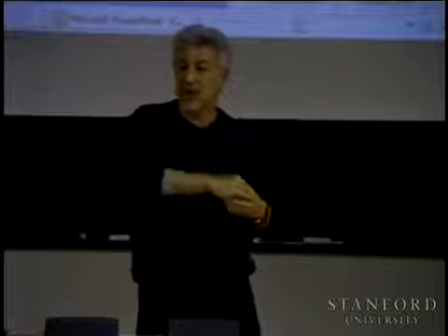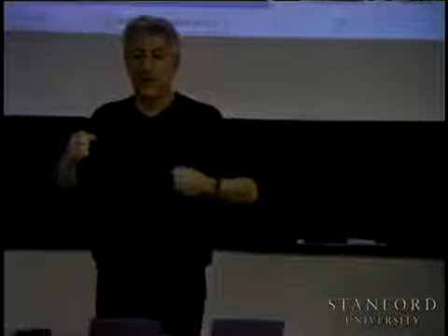Basically, we need the kinematics. And when the thing is moving, it generates dynamics, right? So you need to find the inertial forces. If you move the right hand, suddenly everything is moving, right? You have coupling between these rigid bodies that are connected. So we need to find the dynamics. And once you have all these models, then you need to think about a way to control the robot.